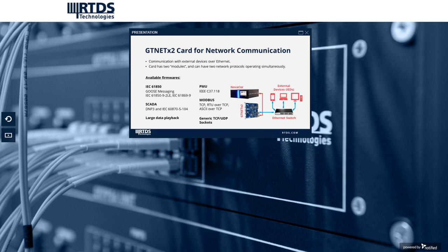And the first is shown here. It's the GTNet X2 card. So the GTNet allows the RTDS simulator to communicate with external devices over Ethernet, and it has a wide range of different communication protocols. So when you purchase the card, it includes the firmwares that are shown here. So beyond 61850, it also can run SCADA protocols like DNP3, synchrophasor protocols, Modbus, and generic TCP and UDP socket communication, for example. The card has 2 modules, and it can have 2 protocols operating simultaneously, one on each module.